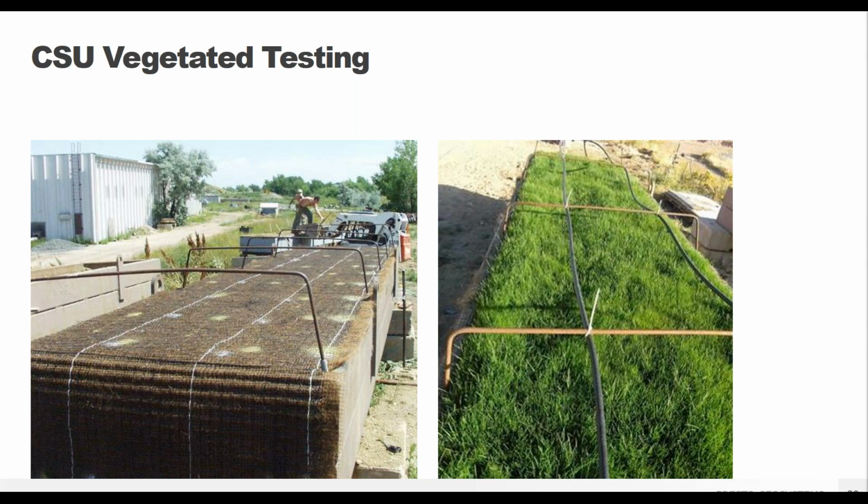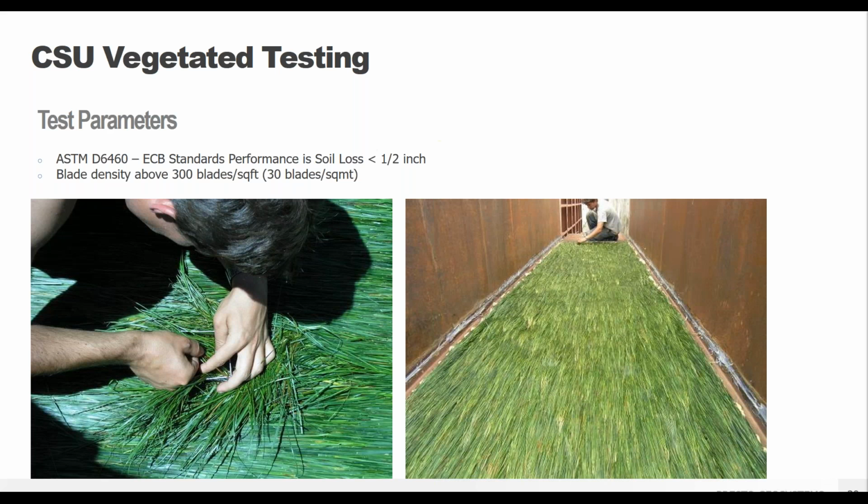The testing consisted of the 6-inch deep GeoWeb panels filled with topsoil, which is probably one of our more common recommendations for this type of project. And then obviously vegetation was allowed to grow to replicate typical field conditions. A total of 10 tests with water flows lasting up to 1 hour were performed with varying conditions for flow rate, bed slope angle, that sort of thing.